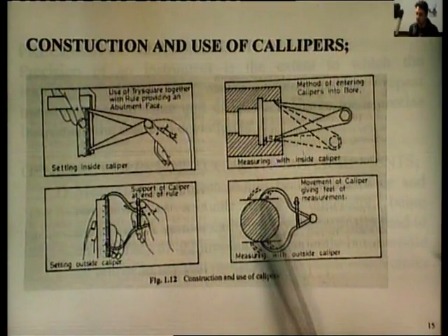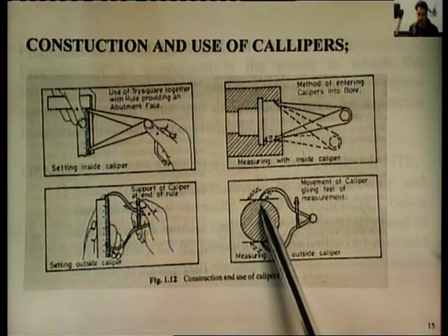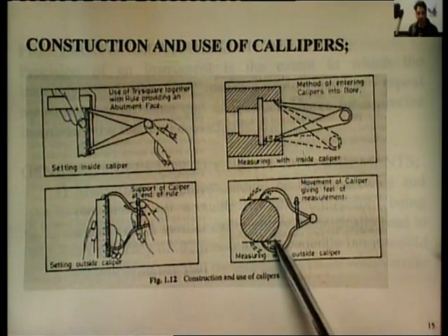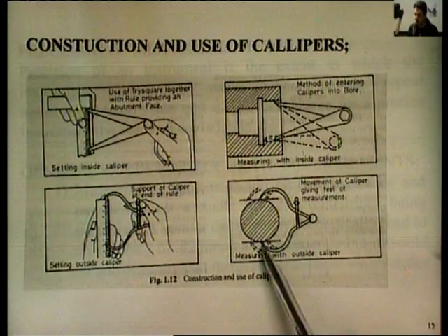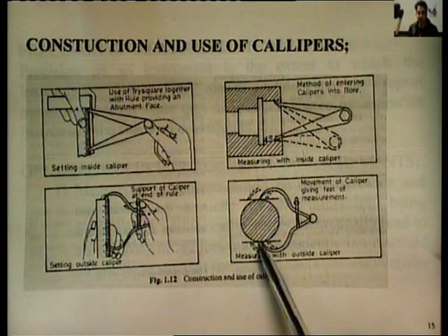So this size, which is the gap between these calipers, can be measured on something else like the vernier caliper, and in this way we will get the measurement. So the feel over here should be right. So this we get with experience.